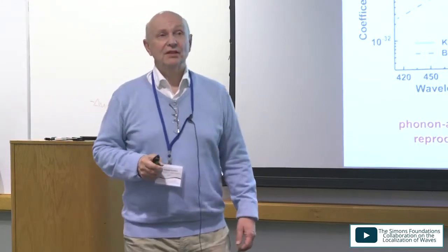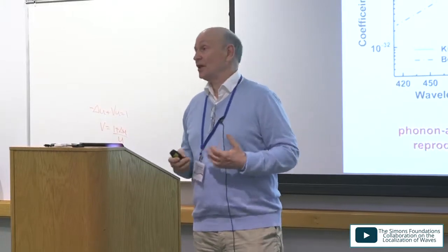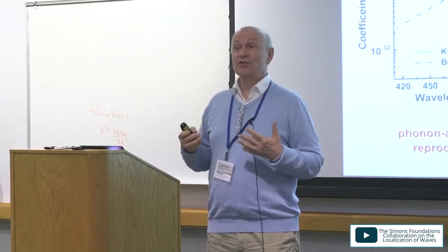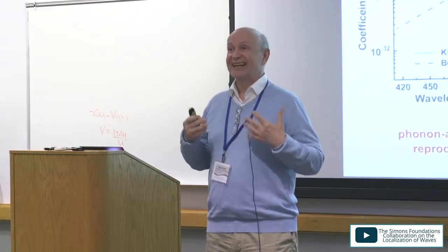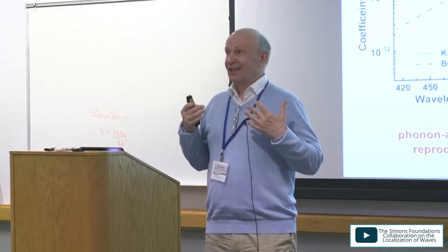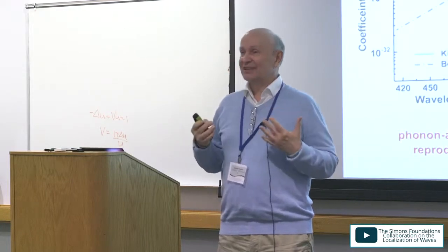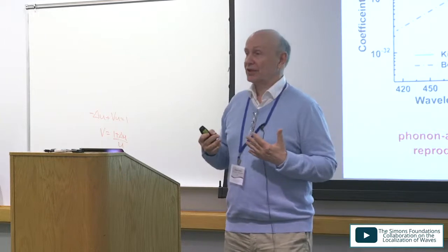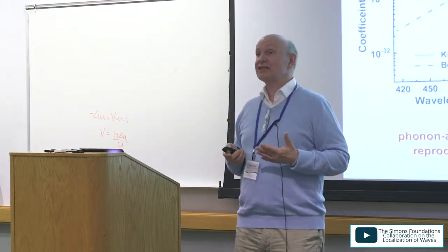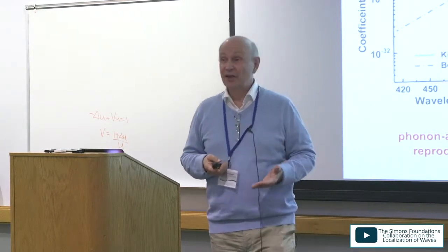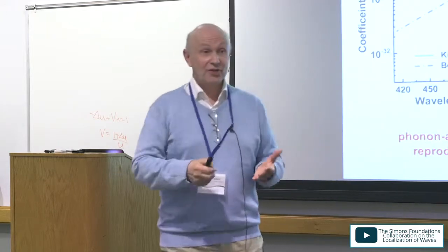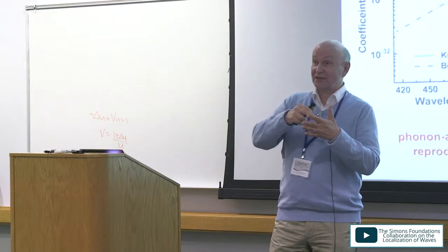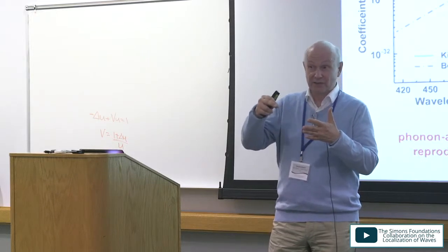Okay, the motivation originates from the drawback of the drift-diffusion model: the drift-diffusion model for nitride semiconductors cannot correctly predict the operation voltage of the LEDs. There are also very interesting experiments carried out at UCSB on unipolar conductivity through an aluminum gallium nitride multi-quantum well.